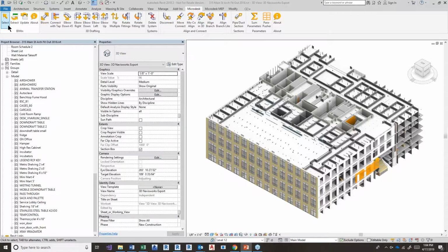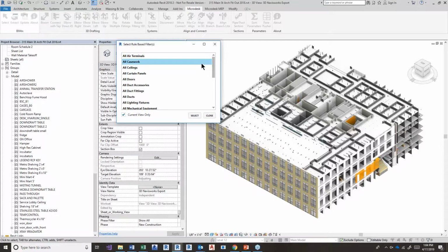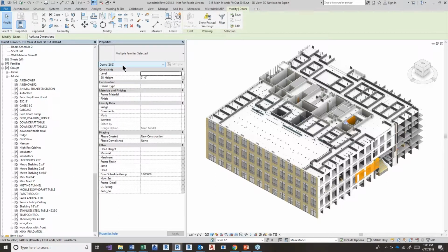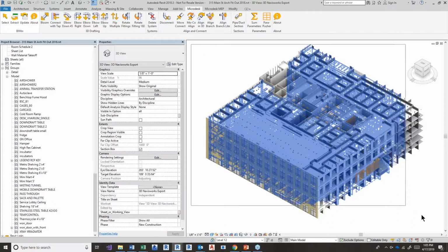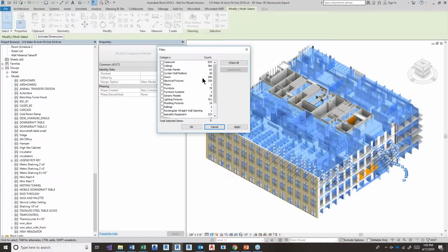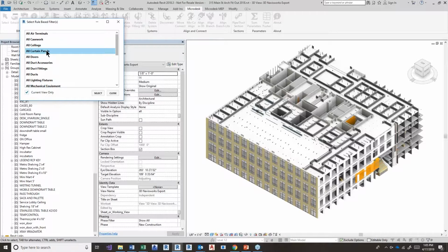Before we get to that, though, along the way, we're going to see BIMrx's selection tool. BIMrx gives us the ability to access view filters to apply to a selection set. So if, for example, I wanted to select all doors in the model, I could do that. And in this case, I've got 286 doors selected now, without the traditional out-of-the-box method of drawing a large selection window around everything I see, waiting for a second as Revit organizes its thoughts, and then clicking on the filter button up on the ribbon bar, deselecting everything and choosing doors. Instead, now I could come through, set up view filters inside of my project template for all of the common things that I want to select.